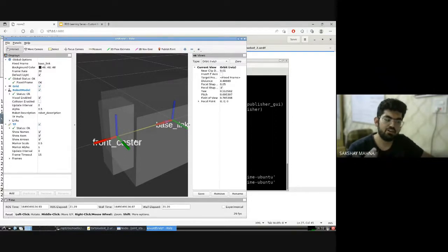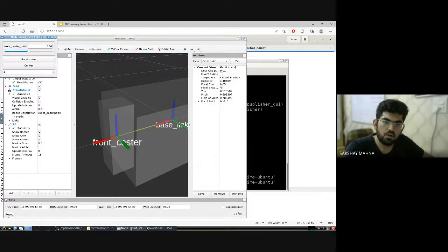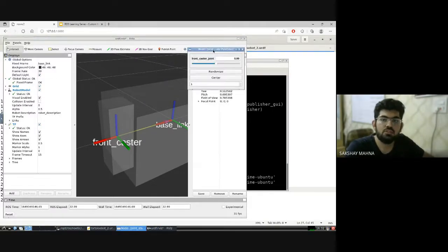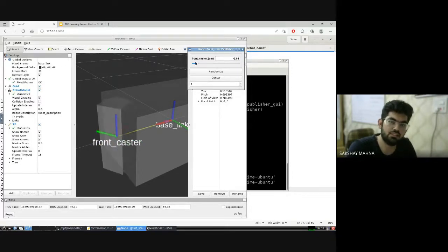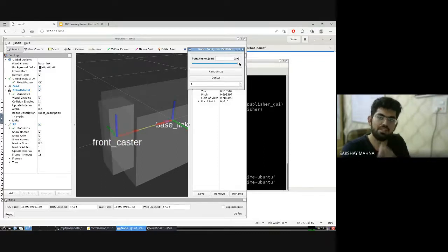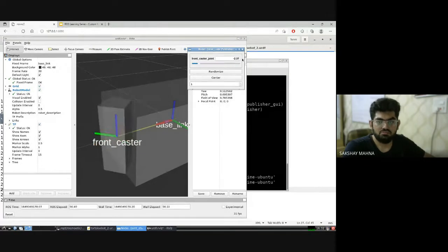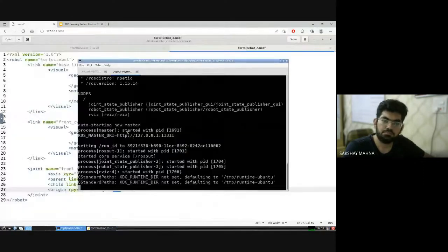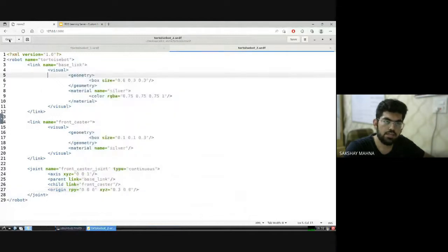When we define complex parameters for RPY and XYZ, that is the complete procedure that is taking place behind the scenes. Apart from that, we set GUI equals true, and that is to show this small window over here. This is just a slider that we can move to see how the joint is moving. As we can see, it is rotating with respect to the Z axis that we set over there. The limits over here are just to demonstrate. Otherwise, there are no limits on the continuous joint. So it can move. We are sure of that. All right, now let's open the next file.